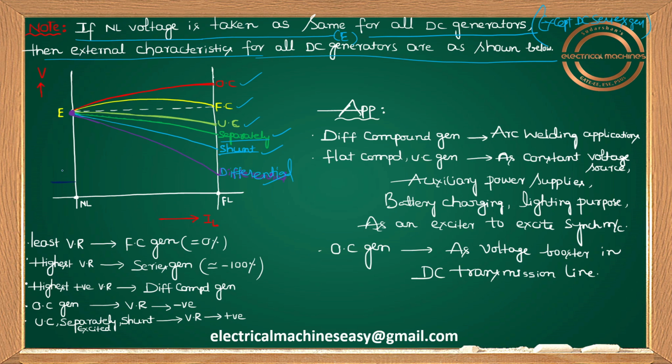What is the no load voltage for this series generator? Almost 0, or I can say residual EMF. Let me take this small value. And as load increases, you are going to have rising characteristics like this. This is for the series generator.